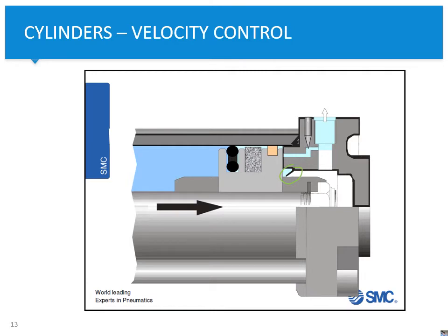So this is one method to keep in mind to reduce the amount of kinetic energy to the back of the cylinder, to the cap end. And this can actually be really useful if you have a cylinder which you want to have really small, really lightweight, and then it can be useful to reduce the cap thickness and use a method like this to reduce the amount of kinetic energy that the cap has to absorb.